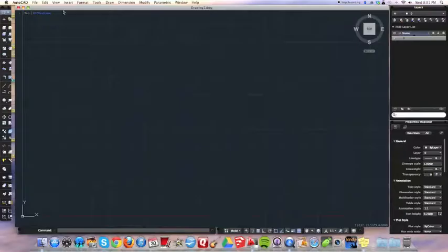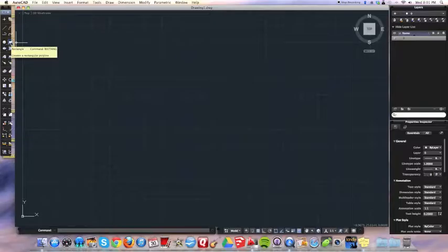We're going to make an oil can similar to the one in the picture. So the first thing we need to do is turn on the drafting tools, and we're going to create some rectangles, but we're actually going to round the corners. Before I even go into that, I'm going to make sure my grid display is on, my object snap is on, my object snap tracking is on, and I'm actually going to turn snap mode on for a little while in this. I'm not going to switch views yet. I'm going to stay in the basic 2D view for now. Top view, cube, nothing messed with there.